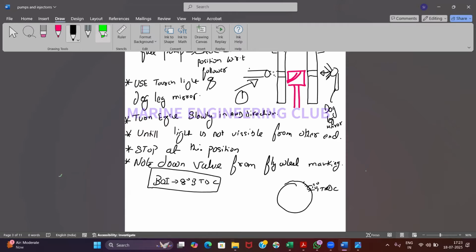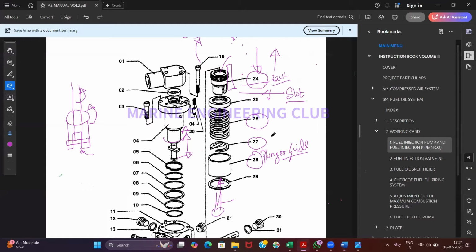Okay. So why do we do this mainly? Just to compare whether the fuel cam is in the right position. See, with time you have to take the timing because certain parts will start to wear off. Here, this is my follower, it is going to hit on this, isn't it? So slowly and steadily your parts will be wearing off. And if the parts are wearing off, my timing is going to change. So you need to check if my timing is correct or not.